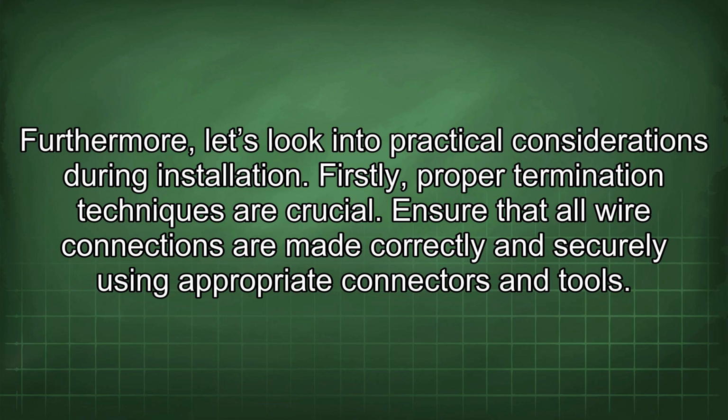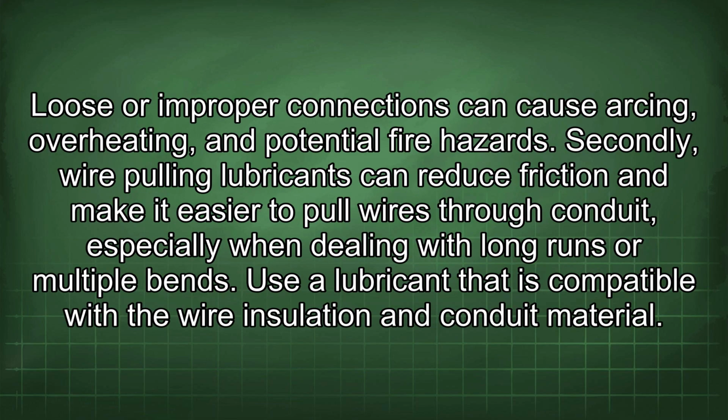Furthermore, let's look into practical considerations during installation. Firstly, proper termination techniques are crucial. Ensure that all wire connections are made correctly and securely using appropriate connectors and tools. Loose or improper connections can cause arcing, overheating, and potential fire hazards.